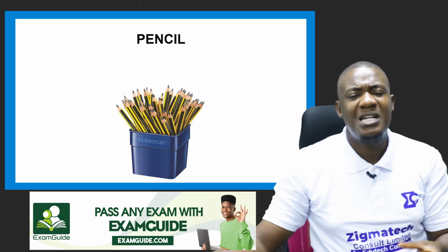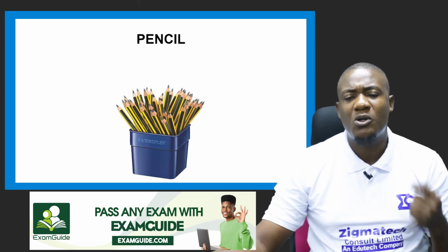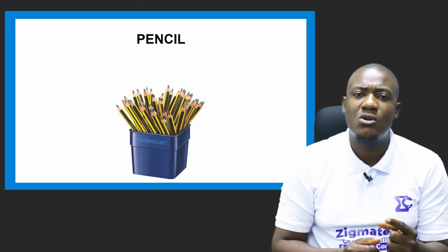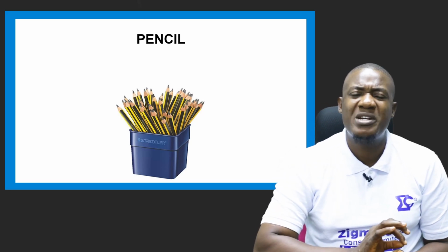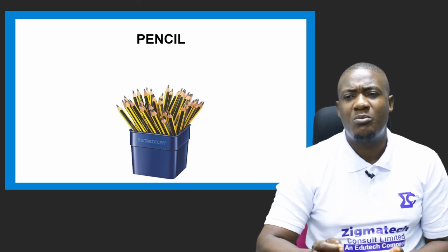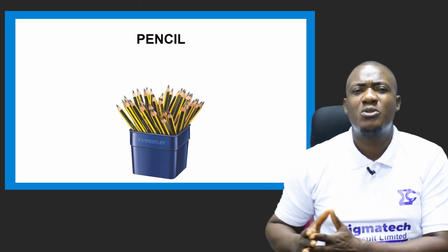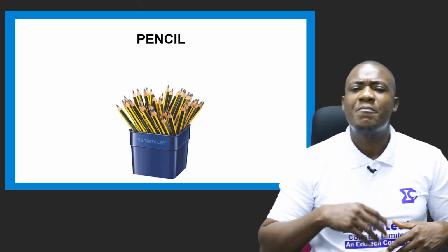So in the hard series of pencil, the lead is hard when compared to that of the bold. That's why it is called H pencils. They don't produce very dark lines. They produce faint lines, light lines, so to say. But the bold series of the pencil produce bold lines. Okay, so oftentimes in technical drawing, we make use of the HB series of the pencil.